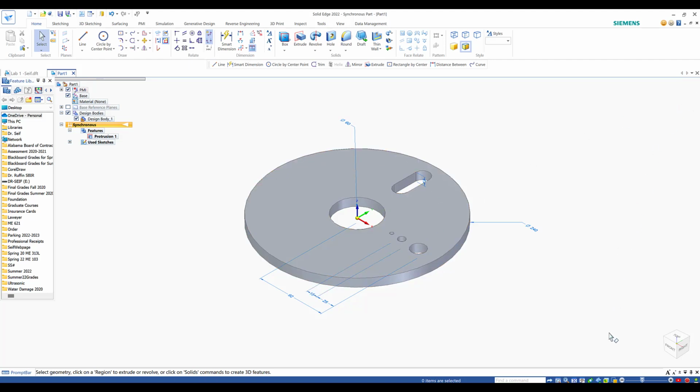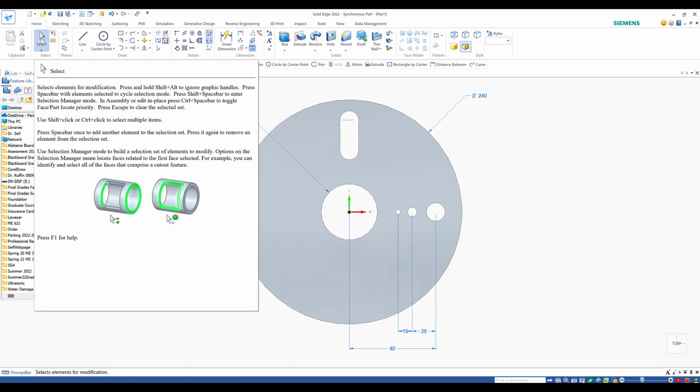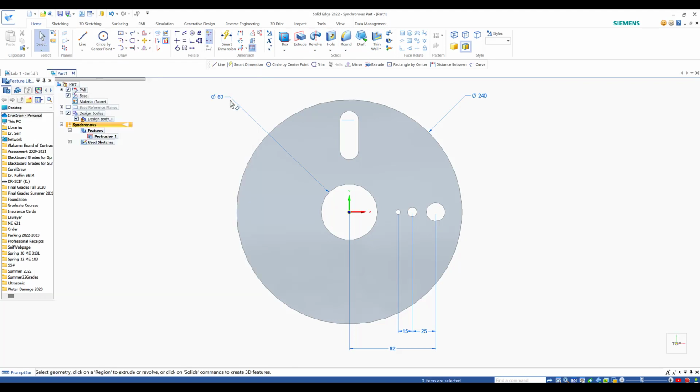Now what I'm going to do is go to the top plane. You see the top plane here? Click on the top. It's going to give you this shape here. Now I want you to watch the pattern here. Nothing is highlighted. But I need to repeat this pattern and the other 3 holes here 6 times. So I'm going to use the select arrow and highlight this one here, the slot here, and I'm going to go down and get these 3.